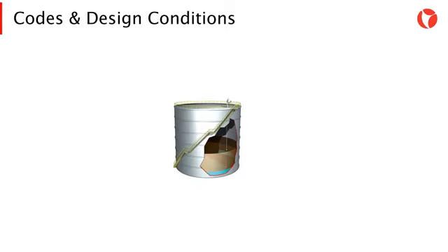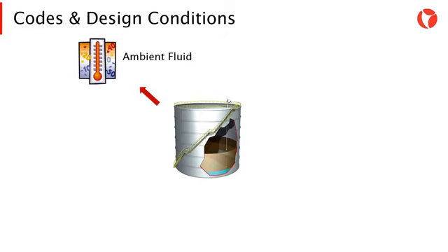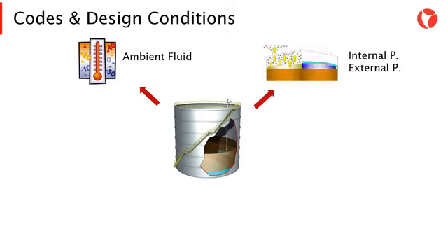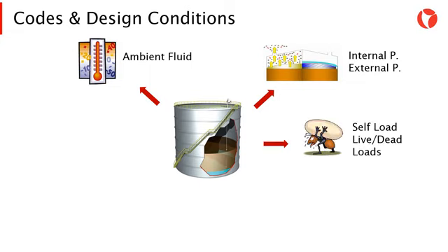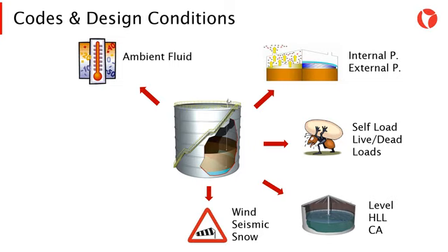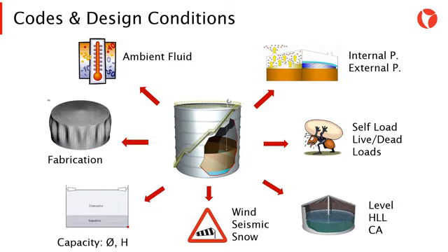Some of them are ambient temperature or fluid temperature, pressure requirements, either internal or external, loading, as in self-loads, live or dead loads, liquid level, corrosion allowance, external requirements, site conditions such as wind, seismic or snow, capacity, diameter, height, and fabrication requirements.